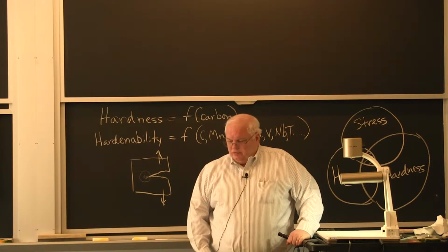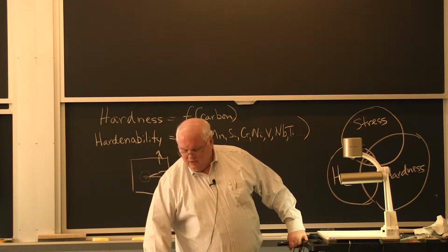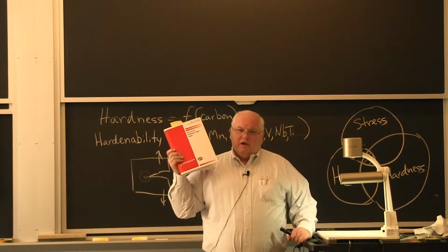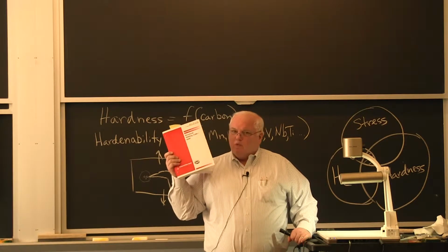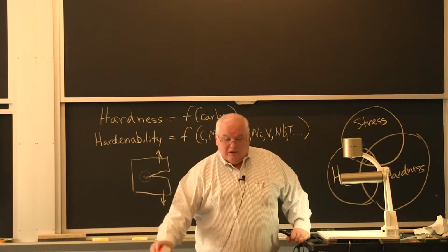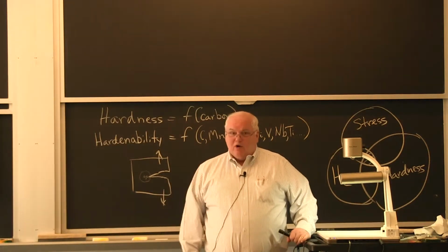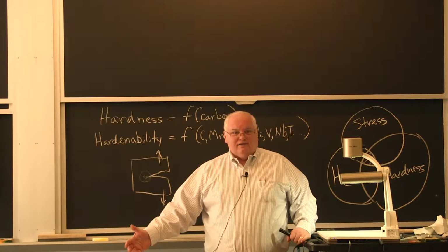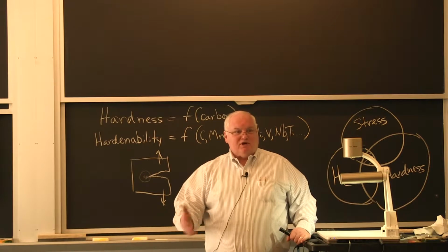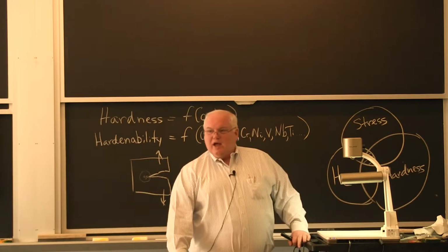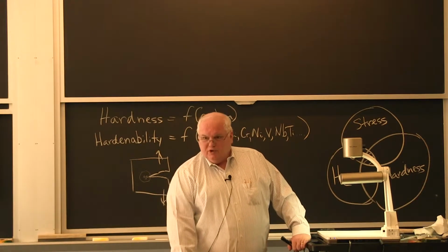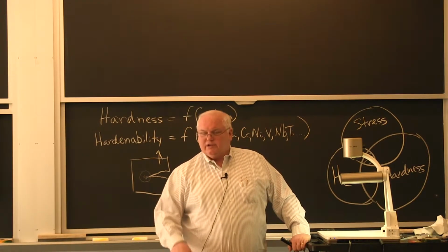It turns out if I go to one of the welding codes, and I'm talking high-strength steels for bridges, this code requires that you not test for cracks in your welds until 48 hours after you've made the weld. Why? Because if you test within the first hour, you might find no crack. And a couple hours later, there might be a crack. And you just missed it because you tested too quickly. You have to sit for 48 hours before you can do your non-destructive testing if you're building a bridge or a building out of 100 KSI steel.